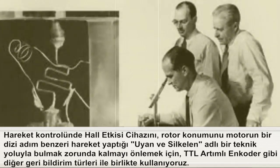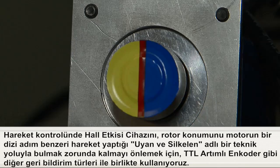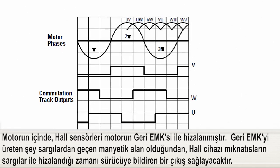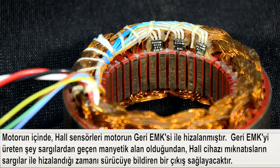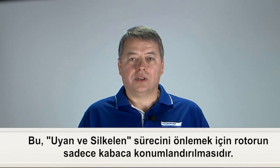In motion control, we will use Hall effect devices in conjunction with other feedback types, such as TTL incremental encoders, to prevent having to find the rotor position through a technique called wake and shake, in which the motor makes a series of step-like moves. Inside the motor, the Hall effect sensors are aligned with the motor's back EMF. Since the magnetic field passing through the windings is what produces the back EMF, the Halls will provide an output telling the drive when the magnets are aligned with the windings. This is only a coarse positioning of the rotor, used to prevent wake and shake.